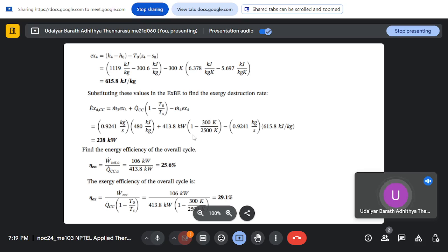So with that, I have finished what I have prepared for today. So the main takeaway here was, in the Rankine cycle, using a reheat and all improved your cycle efficiency. May not generally improve, but the main idea of using a reheat there was to improve your quality at the exit of the turbine. So you may find cases where you have a lower efficiency, or may not find a higher increase in efficiency.